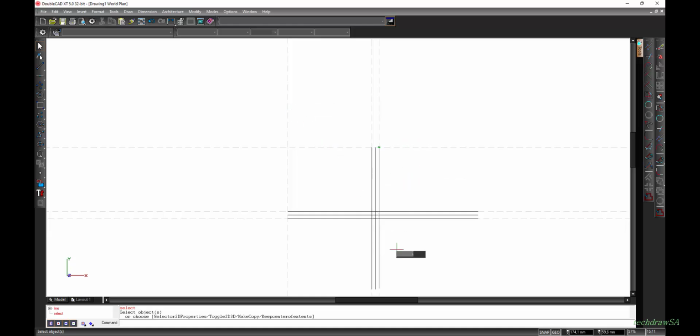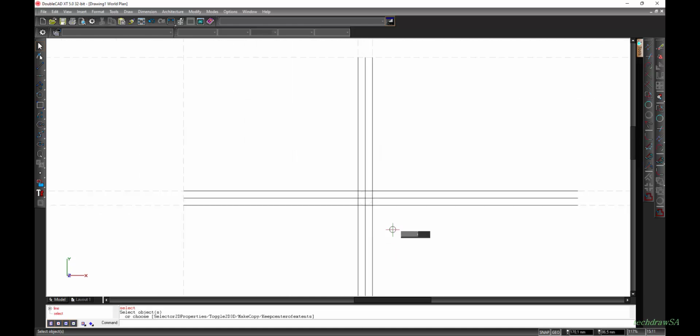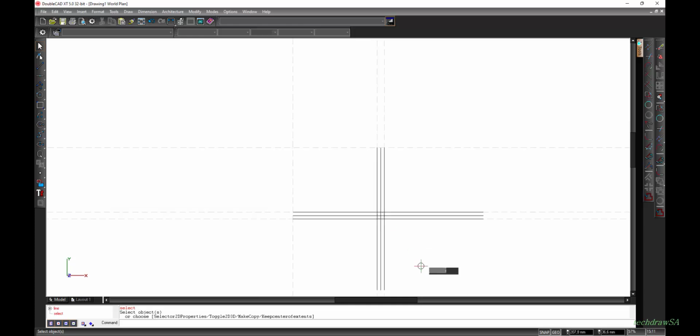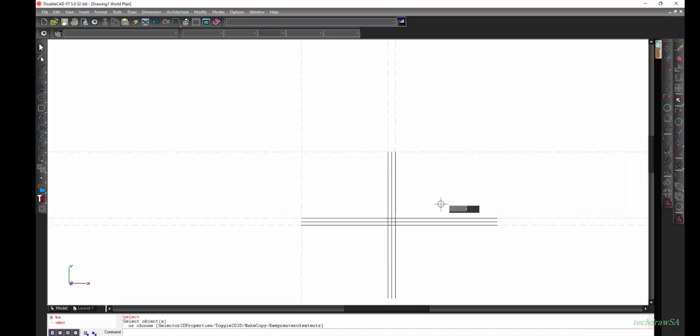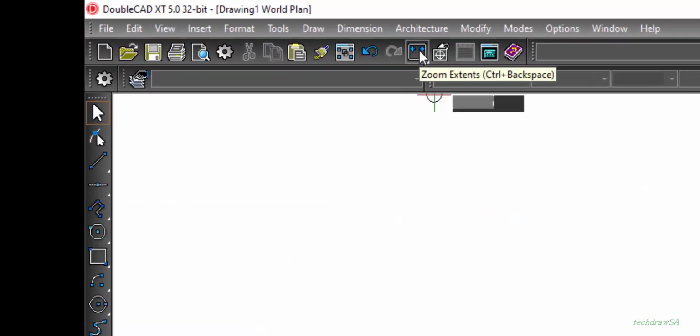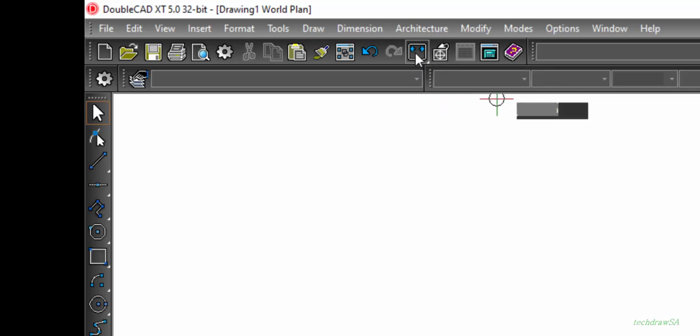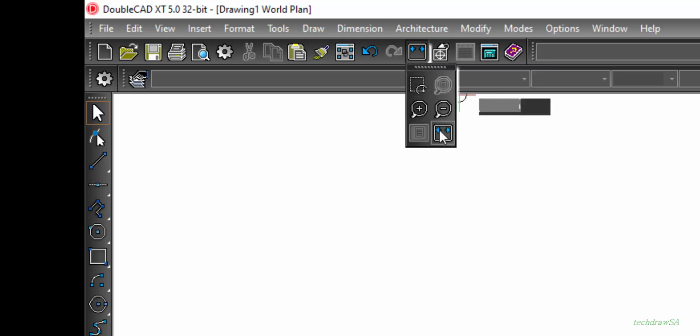And then if you want to, instead of zooming in and out every time, to have this immediately on the whole maximum space of your canvas, you will see that here at the toolbar there's a zoom extends option. Now if you don't see that little rectangle with the blue arrows, you click and hold on any one of these and it will appear on your toolbar.